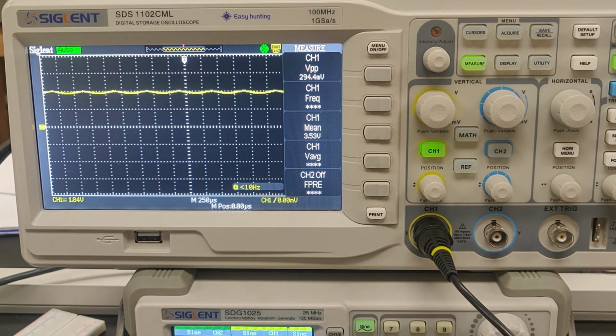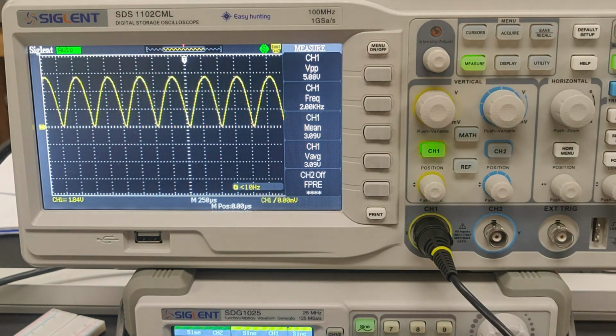And on top, what we noticed with the half-bridge rectifier is that it does turn this AC signal into a DC signal, but because our full bridge rectifier, before adding in the capacitor, already flips it, so it decreases the distance between our peaks, the amount of time that is given for our capacitor to discharge is much less, so we can use a much smaller capacitor and effectively get the same kind of sustained discharge between our two peaks.